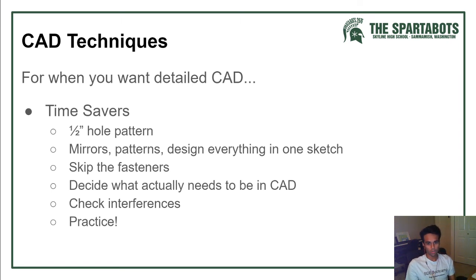Use the mirror tool and pattern tools when designing everything in one sketch. The mirror and pattern tools are really useful when you either have symmetric assemblies or parts, or when you have long pattern parts or assemblies. You should try and aim to keep most of your mechanisms symmetrical for the mirroring capabilities.